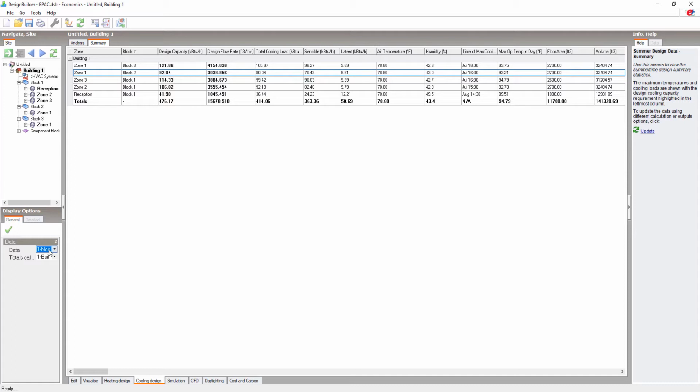Detailed HVAC and EnergyPlus airflow network options are available for detailed modelling stages, for LEED compliance, etc. Natural ventilation modelling with the EnergyPlus airflow network is orders of magnitude faster and easier in DesignBuilder. I know a few modelling experts who really do squirm at the thought of natural ventilation modelling after trying this using the IDF editor and similar tools. So if you've ever been put off modelling it in EnergyPlus, you should try natural ventilation modelling in DesignBuilder. I guarantee you will be pleasantly surprised.